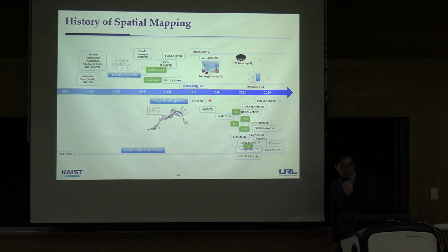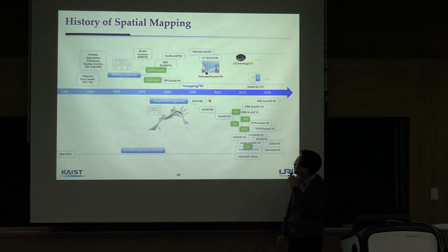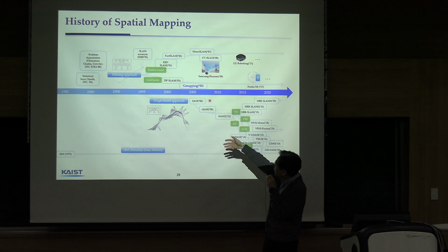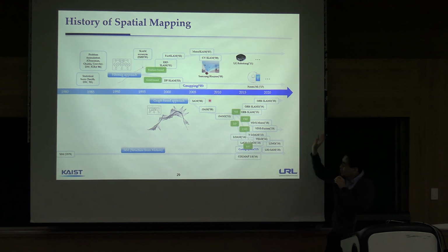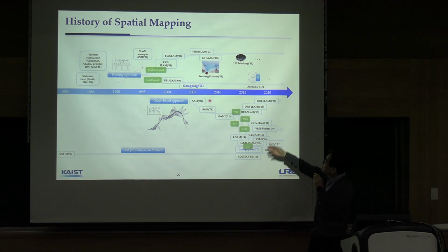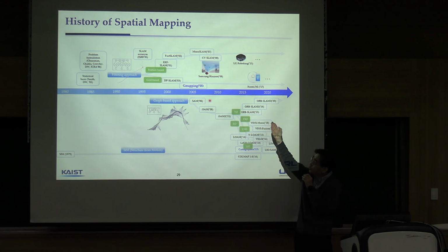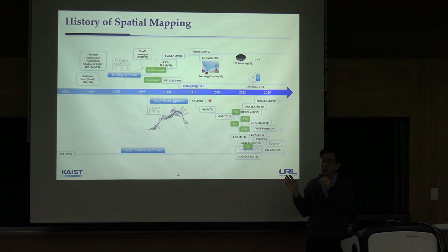This shows the history of SLAM. So the graph-based approach and the filtering-based approach separately evolved, but commercially available products like the cleaning robots mostly use the filtering approach because it requires less computation time compared to the graph-based approaches.